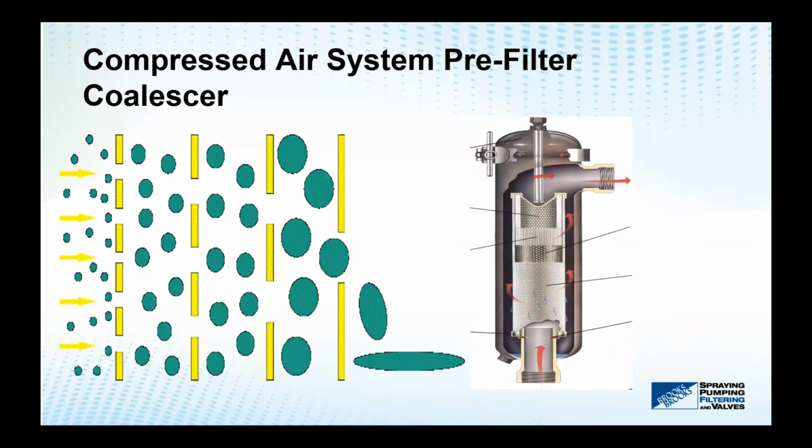Yeah, we've had a few cases in the field where customers have short life on a coalescing filter, and what they'll do is simply place one of those Eaton separators upstream, in front of the coalescer, to knock down rust, pipe scale, whatever kind of contaminants are causing the coalescer to build pressure drop. And usually the cost of putting in the Eaton system is paid back in a short period of time, because the coalescing filter doesn't have to be changed out as often.